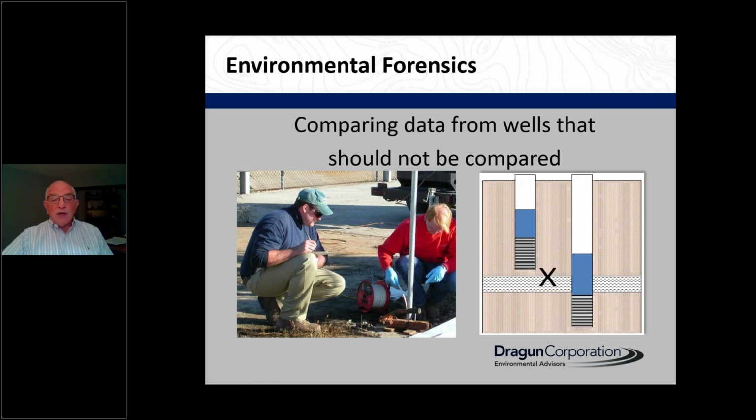In other cases, we've seen wells put in where they're trying to determine if there's free product gasoline on the water table and the wells are too deep. You'll never see the free product. So we need to be able to get our wells right.